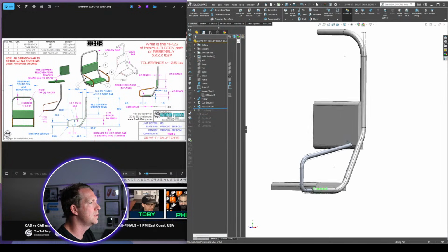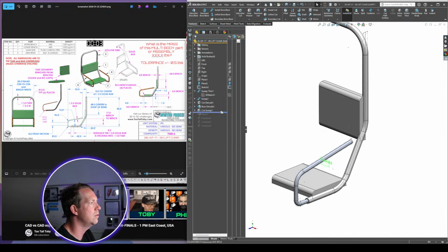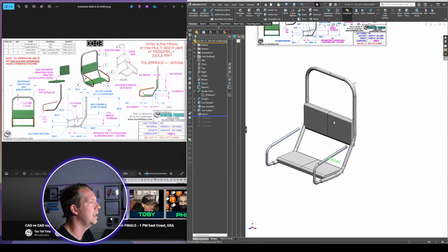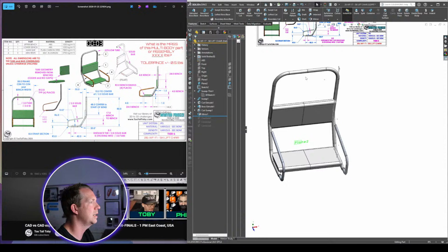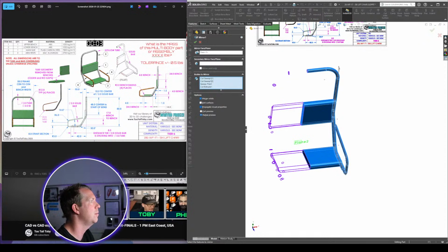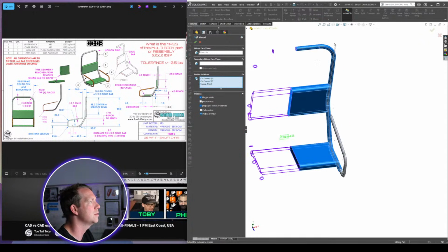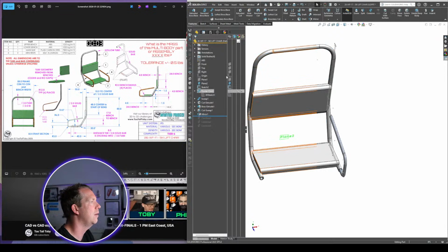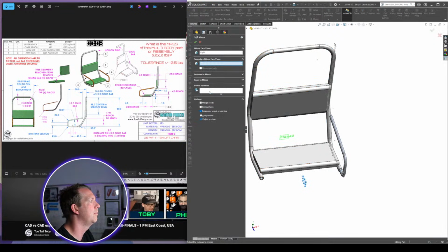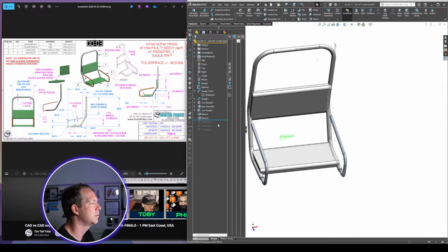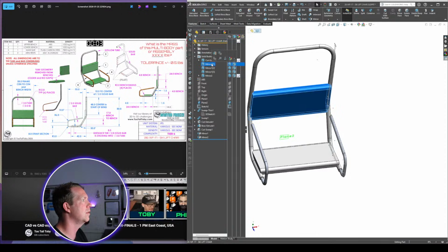I did do the seats in half though, which means do half and then mirror them. And again, to Utse's point earlier, I could actually mirror and merge those, and that would save me a bit of time. So if I go merge solids, if I remove this body here and just merge these ones, that works. And then I can do a separate mirror just for this one. I don't need any of those combined features then. That's going to save me quite a bit of time.